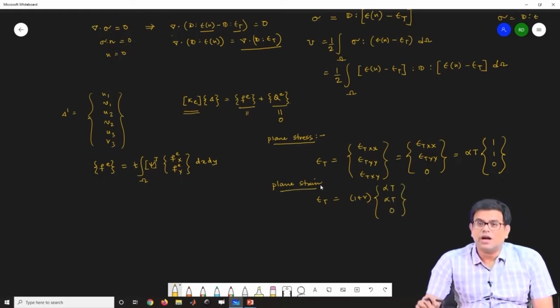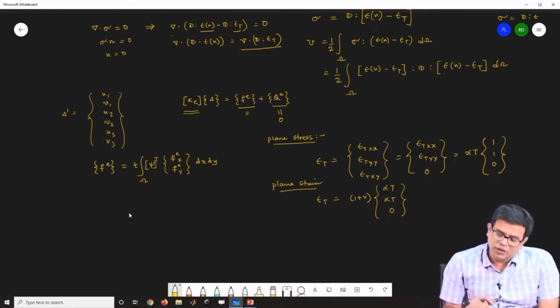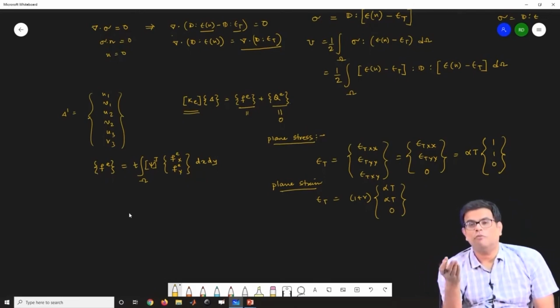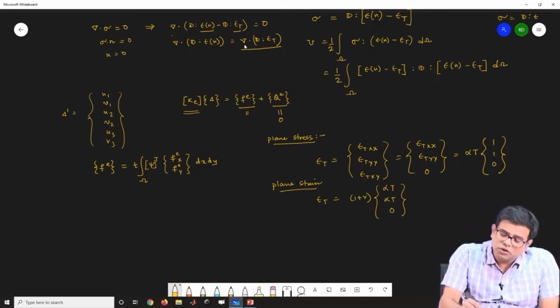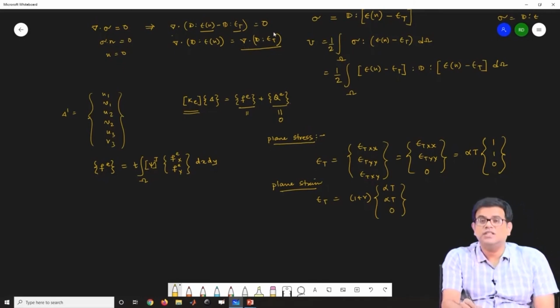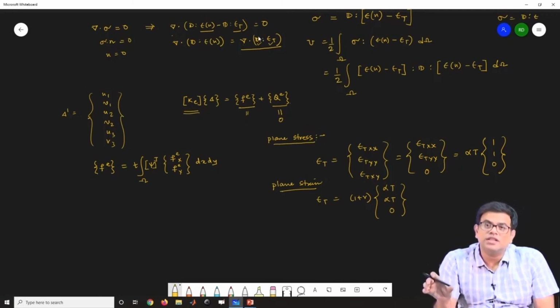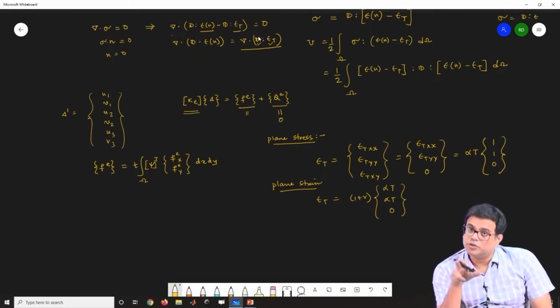Now once we know the thermal strain, then you also know the thermal stress. Naturally, your weak form will again involve the term del dot D epsilon T, the thermal stress. You know D, you know epsilon T, and then in the weak form you will get the forcing term, which will contain the B matrix, that is the strain displacement matrix, because of the derivative of the weight function.